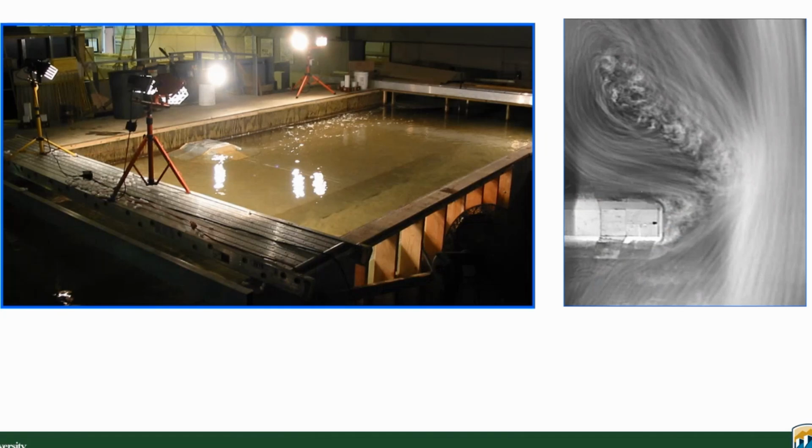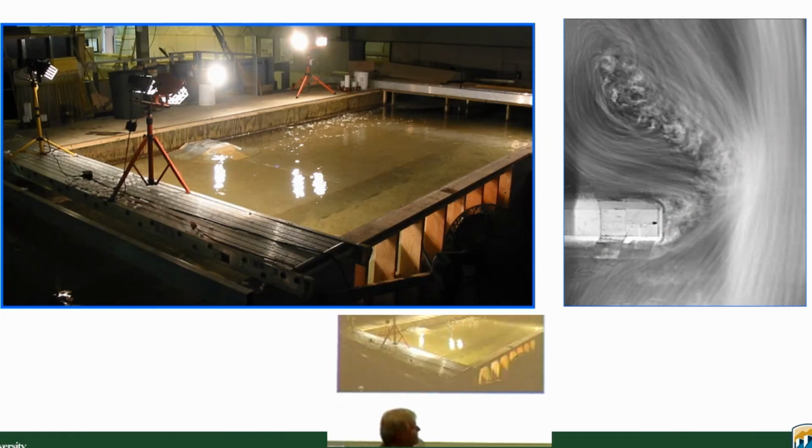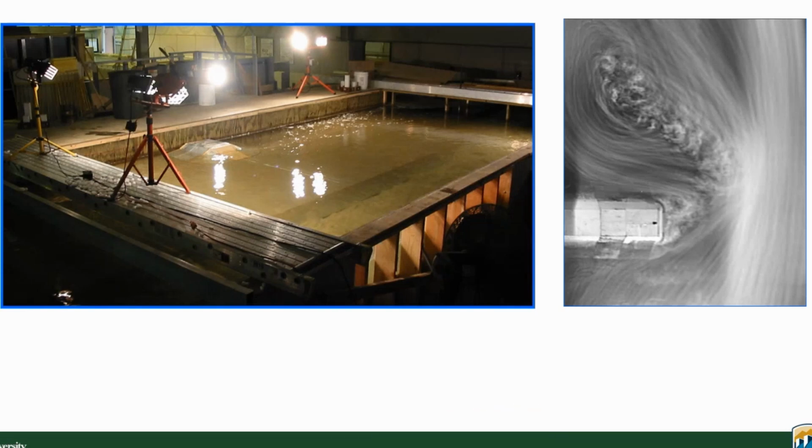These days we have more instrumentation, but just to point out here the complication of the flow field in plan view, and this is illustrated using large-scale PIV, which is a method that we use increasingly these days. So you have the flow contracting around here, you have turbulent structures and so forth, and the deepest scour is in the vena contracta for this type of spill through abutment below the downstream edge of the bridge.